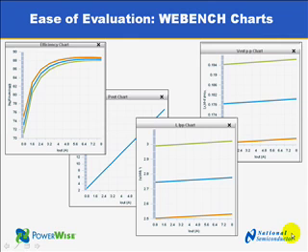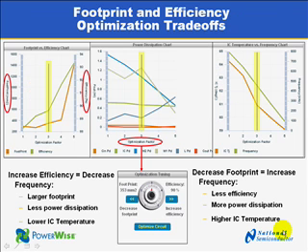Here we show you some of the charts that are available. Top left is an efficiency chart, from a different design, and it shows efficiency over output current, as before. To the top right, you see, for instance, a VOUT peak-to-peak chart that gives you basically data about the ripple on your output voltage. These are optimization charts. With the optimization dial shown here, you can choose in 5 steps your optimization, and basically we talk about efficiency over footprint. And that is also shown in this chart here.